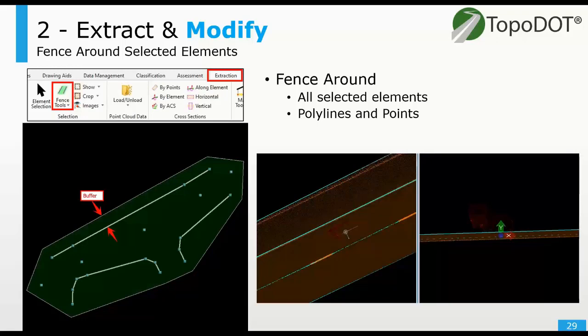Seen on the right, I've used some road lines to isolate the roadway surface, and then follow up with a classification routine for removing vehicles. So we can see that vehicle in red. That way I'm not running a classification routine off to the shoulder where I might have signs and poles and overhead objects that I want to keep. This is one way to isolate it onto like a road surface.